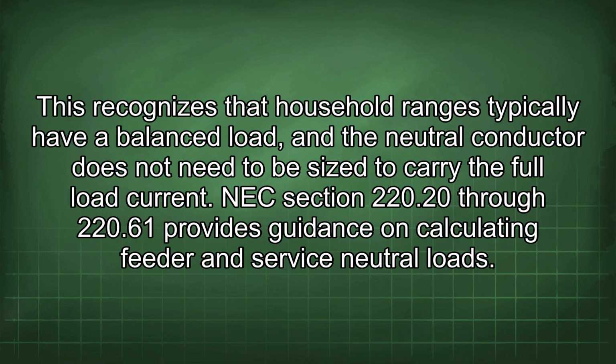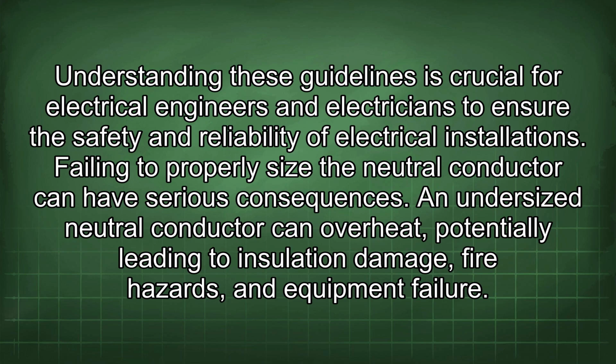This recognizes that household ranges typically have a balanced load, and the neutral conductor does not need to be sized to carry the full load current. NEC Sections 220.20 through 220.61 provide guidance on calculating feeder and service neutral loads. Understanding these guidelines is crucial for electrical engineers and electricians to ensure the safety and reliability of electrical installations. Failing to properly size the neutral conductor can have serious consequences.